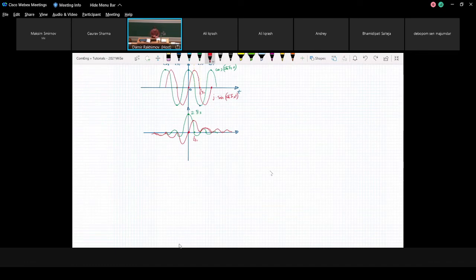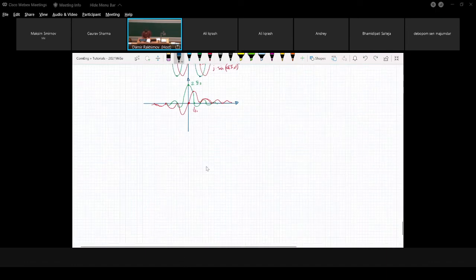And the last part that we have to solve, we have to find the output signal in the corresponding low pass range. Go to part D. Determine the output signal and spectrum in the low pass range, the equivalent low pass range, because we already have the signal in the band pass range.